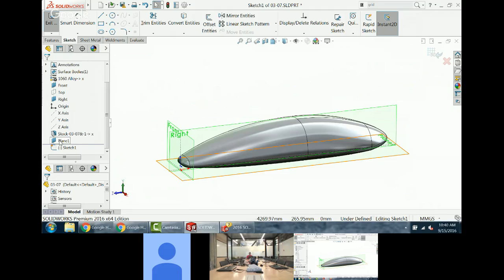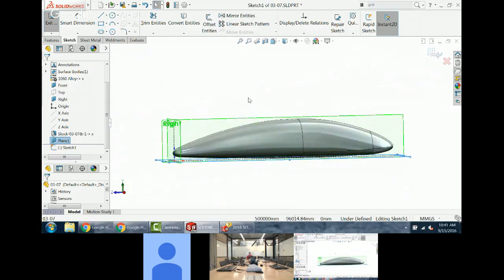In a sketch, and my sketch is on either the top plane by default or whatever plane I had selected. What this tool allows you to do is quickly build up a lattice work. So it's really great if you're building power towers, derricks, cranes, staircases, scaffolding, stuff like that. We've got levels and places you want to quickly put in sketch geometry.